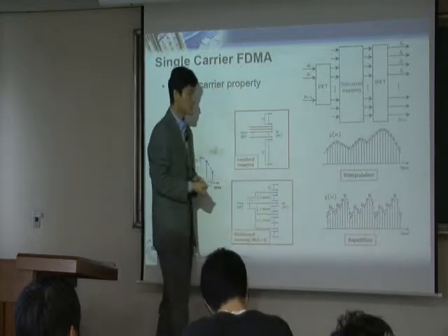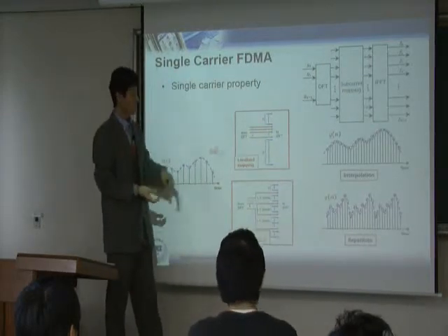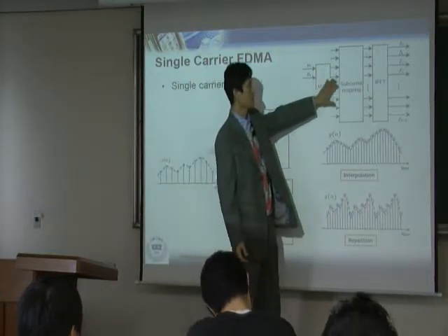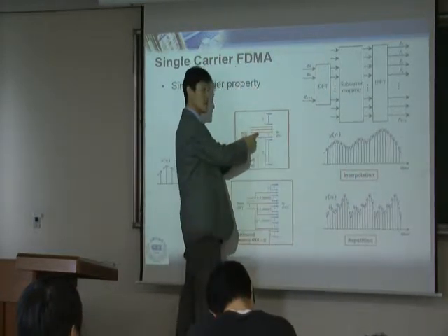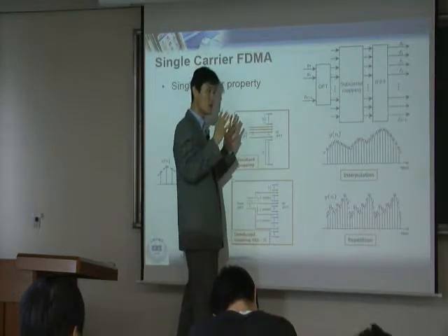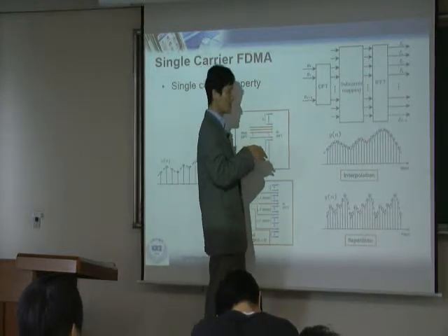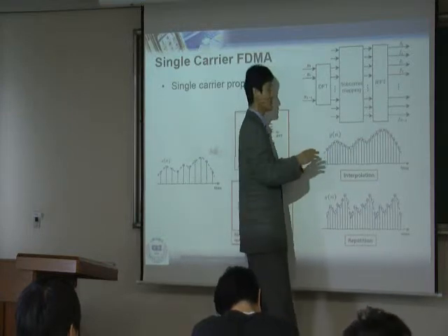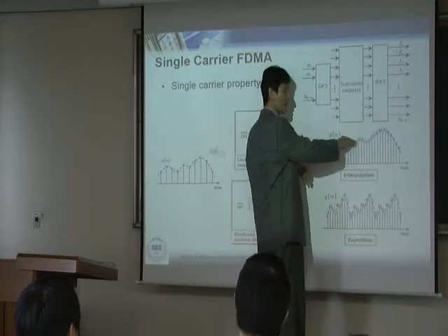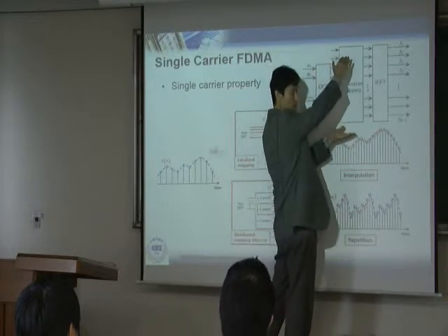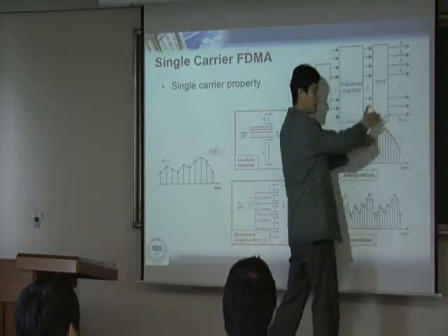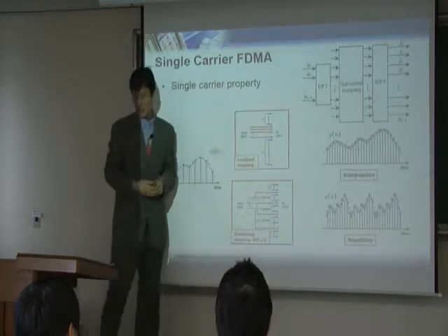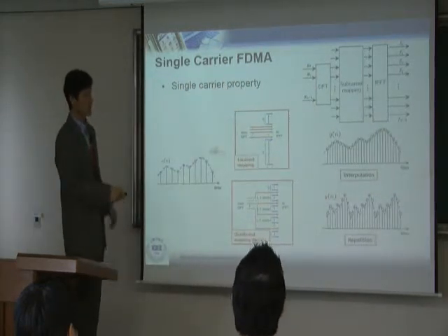Then what happens is you are doing interpolation. You still have the same number of samples in the frequency domain. You didn't change anything, so your frequency response is still maintained. Your time domain envelope is still maintained. The only thing is that you added some zero padding, therefore you have more samples. Go back to time domain, and you simply have more samples in the same envelope. So that contributes to interpolation.